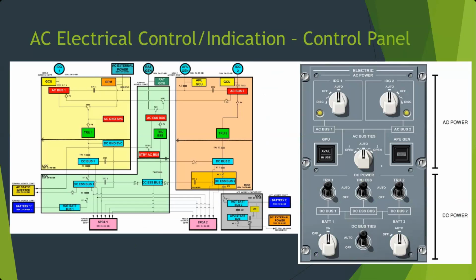When the engines are running, the generator comes on and automatically starts powering its respective bus. When the engine shuts down, the generator stops spinning, it stops putting out power, and the generator turns off. You don't actually have to turn it off. You restart the engine, the computer senses the generator's up to proper speed, and it makes the generator put out power.